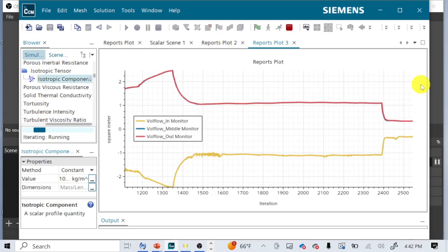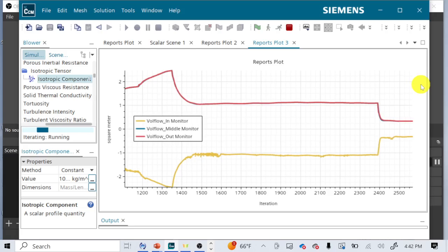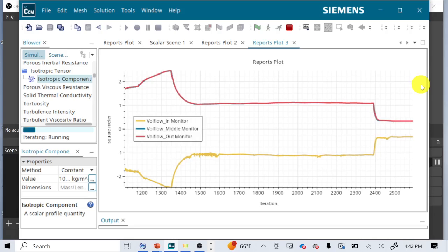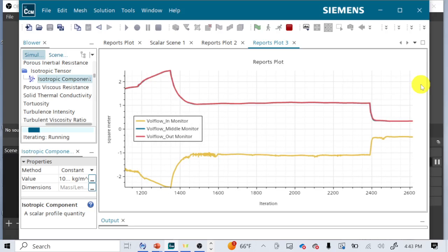So we actually probably want to look at 2 different fan curves that are typically plotted. One of them looks at static pressure, one of them looks at total pressure. In principle, let me just redraw this, clean it up a little bit. We want to get a plot, actually multiple plots, with delta pressure on the y-axis and volumetric flow rate on the x-axis. We want to get at least 6 fairly widely separated points on this so that we have an idea of what this curve looks like. We should be able to choke off this fan. If we crank up the resistance high enough, we get damn near 0.